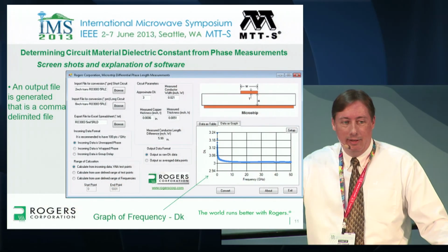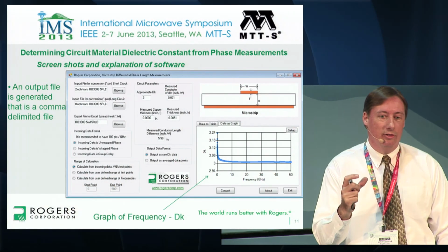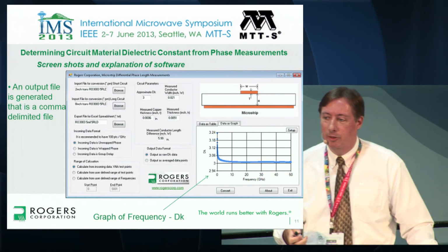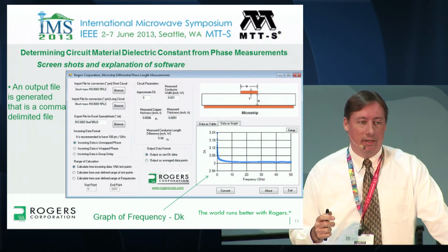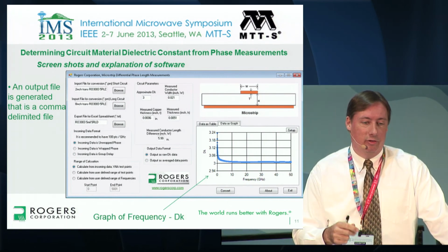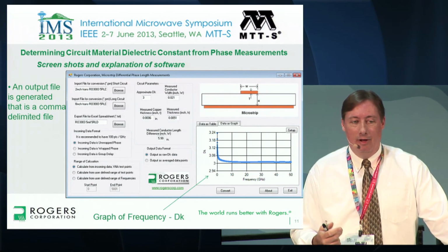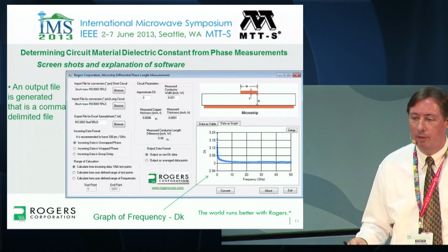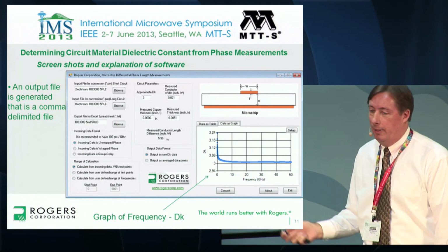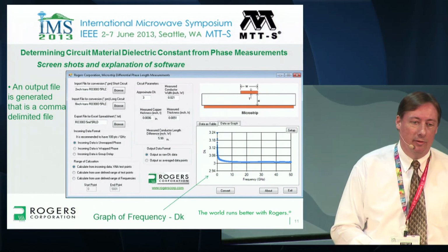And what you get is these dielectric constant numbers that go up into the hundreds of thousands, and that's just because the shorter circuit is no longer acting like a transmission line. So if you really want to look at microwave at lower frequencies, the shorter circuit probably shouldn't be a 2-inch circuit. You might want to try some other things like a 4-inch circuit and 6-inch or something longer. That gives you a little better response, a little better resolution down at the lower frequencies.